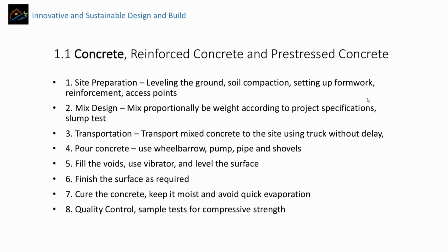After the mix design is made and we have mixed these materials and ingredients, then we transport the mixed concrete to the site using trucks, and it should be transported without delay. There are specific limits on duration, for example, half an hour to a maximum of 1 hour, so that the concrete is transported onto the site in order to have the desired concrete.